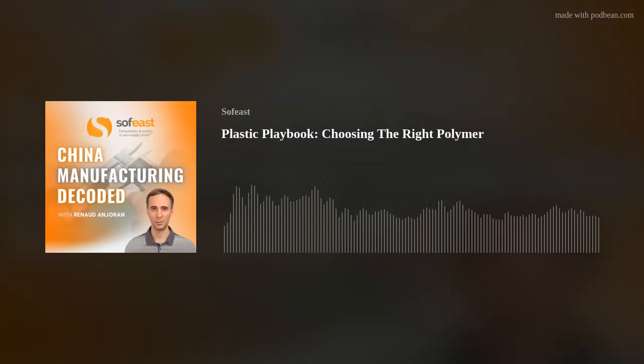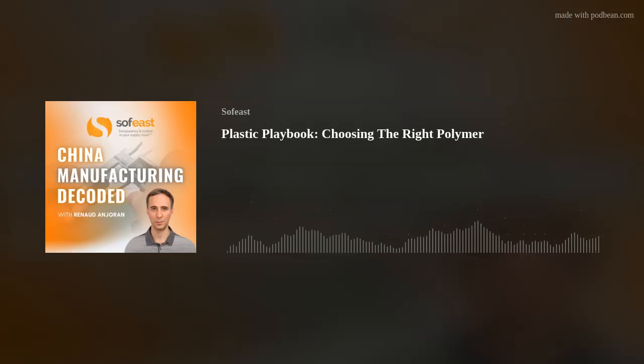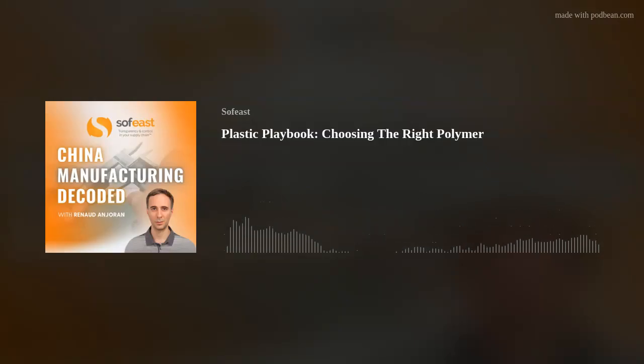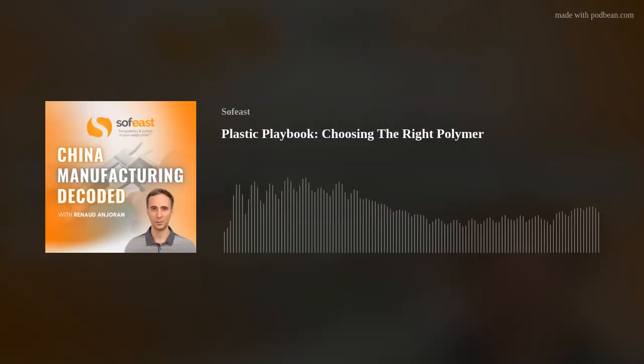The next one I want to talk about in this particular sector is PC or PC-ABS blend. Now, when we're talking about a blend, we're talking about two base polymers coming together to make the set of ingredients to get the final cake, let's say. So we generally refer to any polymer that has been mixed as a blend. Okay, so the PC-ABS has very good improved properties over and above the ABS as it stands.